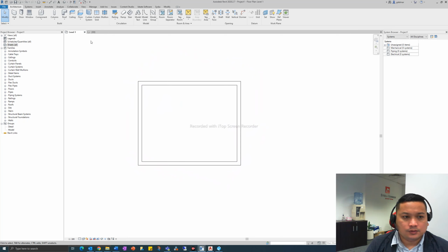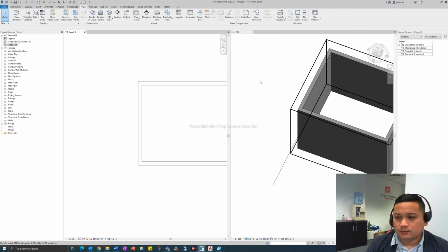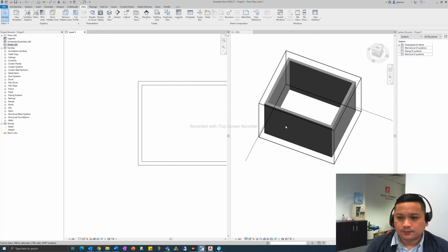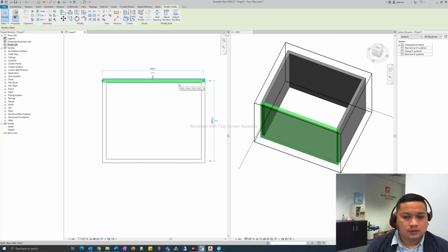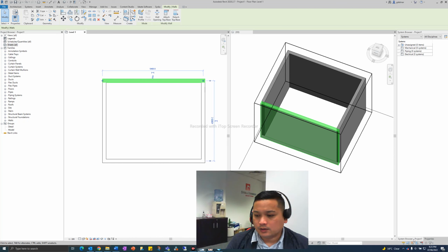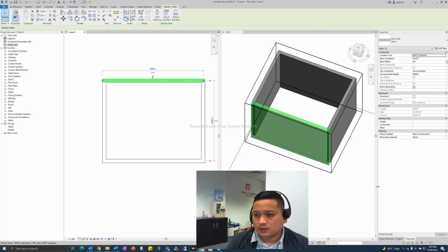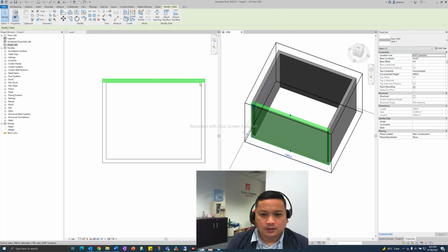Then going back to your view, you can also see two views, like if you want to work from the model and directly see your walls. Then if you go here, you can see the properties. Then you can change the height, the families, curtain walls, you can stack walls, you can replace, all you want to do in your walls. So this is just an overview.